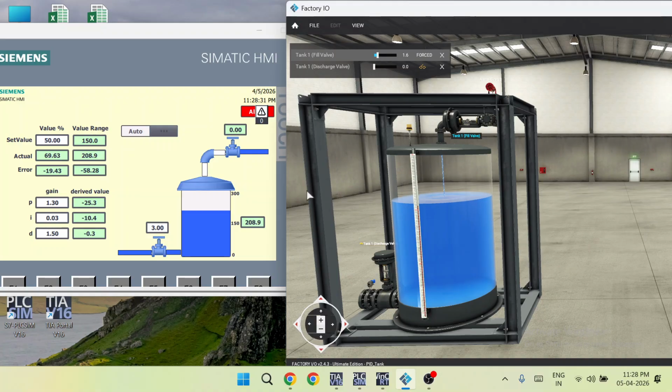Now the PID will detect it: as the PID has kept the valve off but the valve is saturated, the value will keep rising. So the PID will detect the valve is saturated and an alarm will be given.